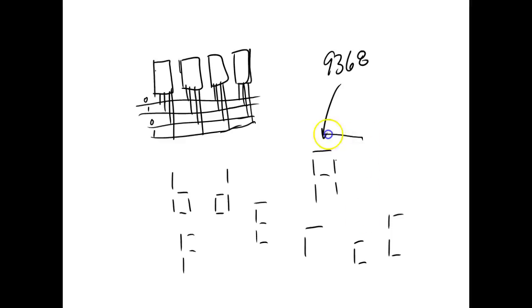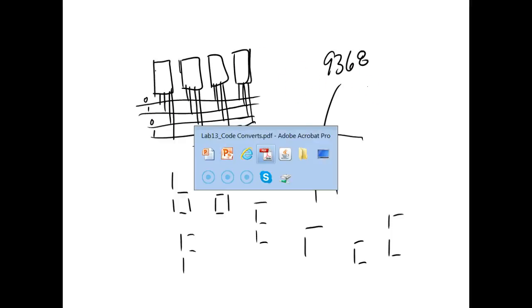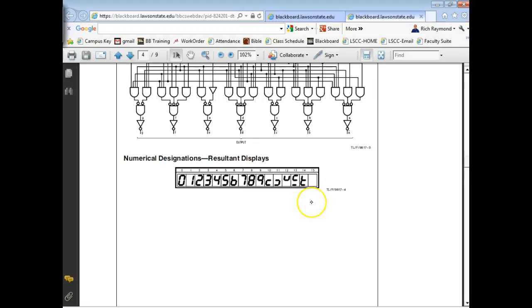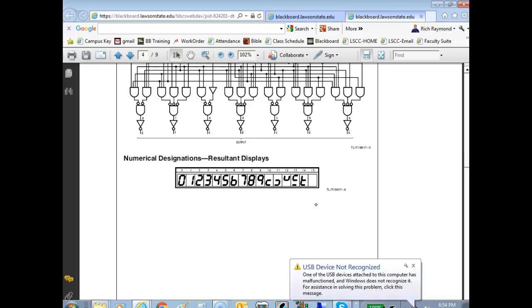But I've worked on devices that use a 7447, and after a time, you learn these codes. So you know what an A is, a B, a C, a D. You learn them after a while, but it takes a little while because the 7447 gives you a code for anything above 9. So it basically does BCD real well, right? You understand? But if you put a 10 on it, it's not going to blow up on you. It'll display something, but it just won't be what we expected to display. That makes sense?